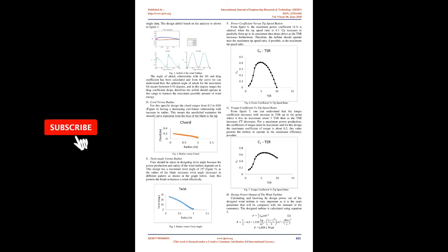Structural performance. A structural performance plot is shown in Figure 2, which includes 5 subplots: shell thickness, stiffness, bending moment, deflection, and first flap-wise eigenmode, all versus the non-dimensional radial position of the blade, r/R. The shell thickness plot contains the dimensional and relative thickness of the shell. The dimensional shell thickness is in meters, black line, while the relative thickness is the dimensional shell thickness divided by the chord, green line. When the cross-section option in the structural data panel is set to solid, the relative shell thickness shown should be a straight horizontal line.